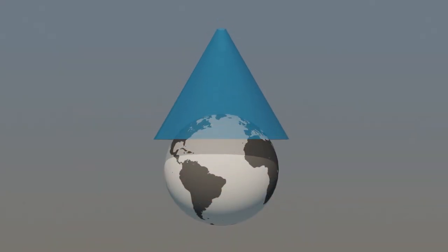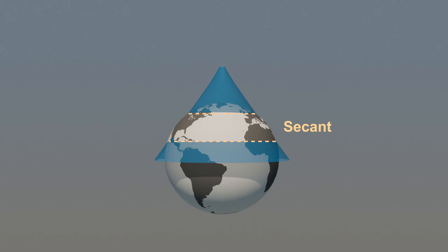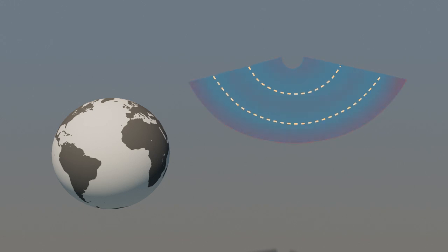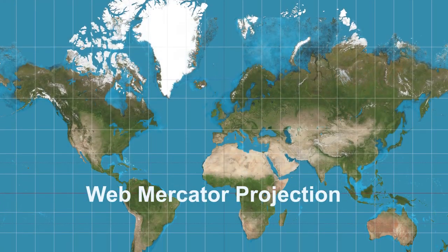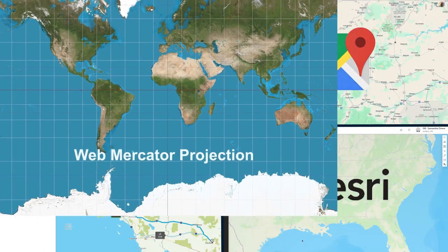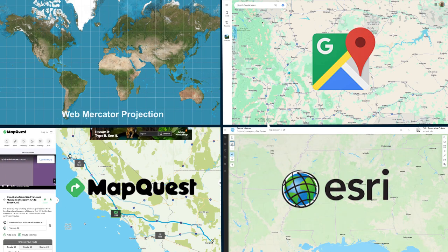Conic projections place a cone where it is touching a globe, called tangent, or cuts through a globe, called secant, and then flattened. The Albers projection is an example of a secant conic projection. The distortion is lowest at the standard parallels and increases with distance from the standard parallels. The map projection commonly used online is the Web Mercator projection, which can be found on online maps such as Google Maps, Esri, and MapQuest.